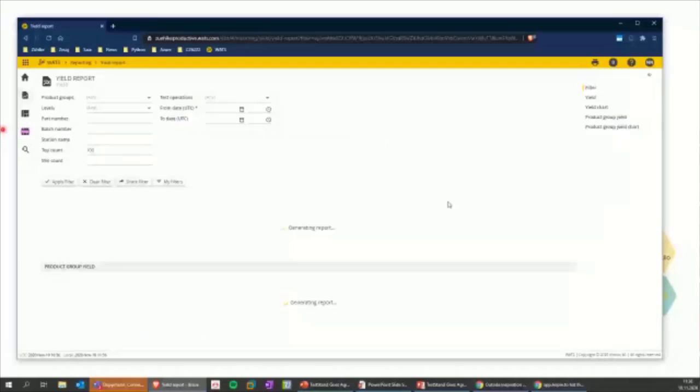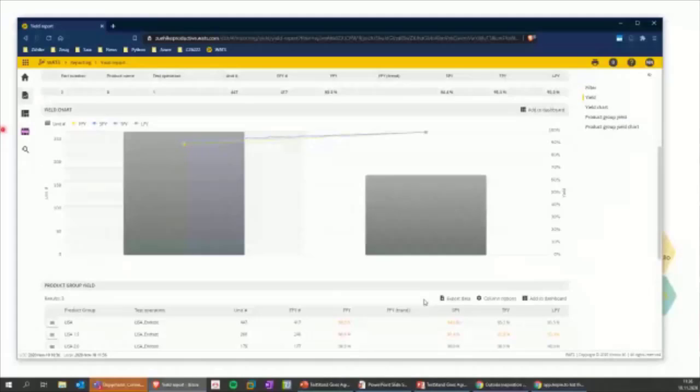And if you go down, you see that there are a bunch of reports, how many passed, how many failed. You can go into each report immediately, but you can also pick something up like the yield report. And you see that we have two different part numbers that are being produced here. The first one has a first pass yield of 89.55, and the second generation of our device has a first pass yield of 98.88. So this is where we would like to be. So we could improve our processes, and you immediately see that, which is really cool.